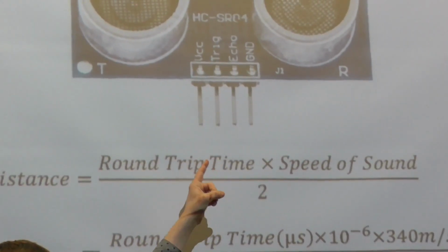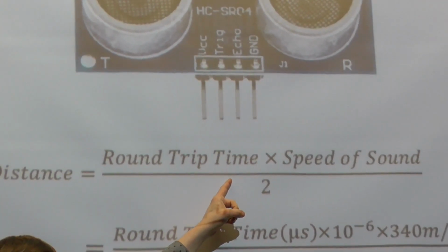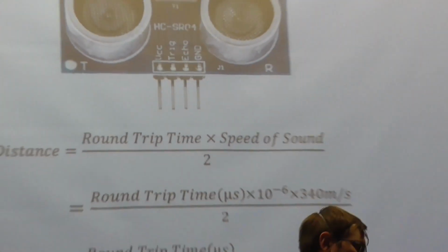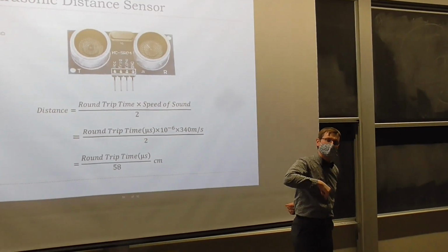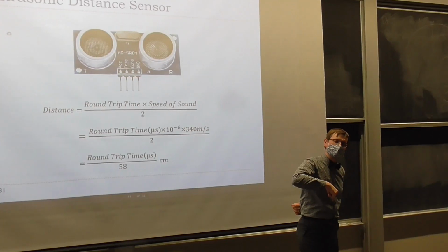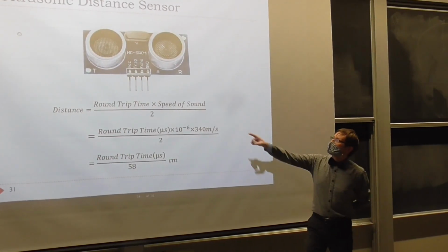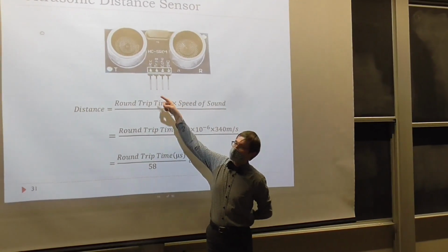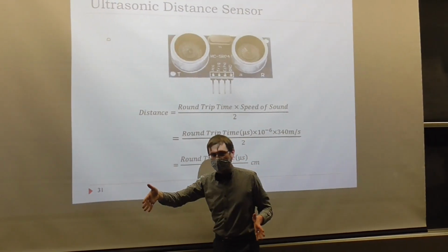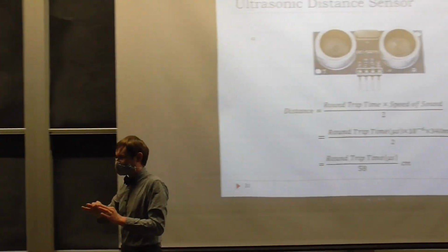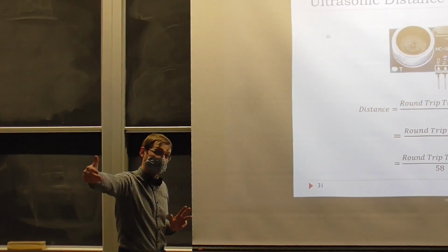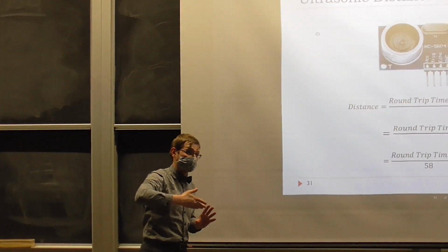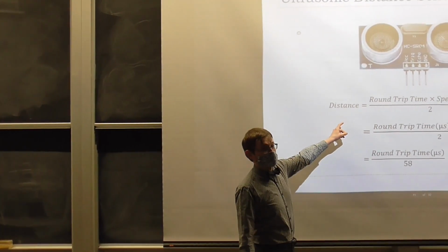So if both of these are being read, then you can measure the distance between the trigger and the echo to determine how long it took the sound to reflect off of an obstacle and then back to the sensor, using this equation.